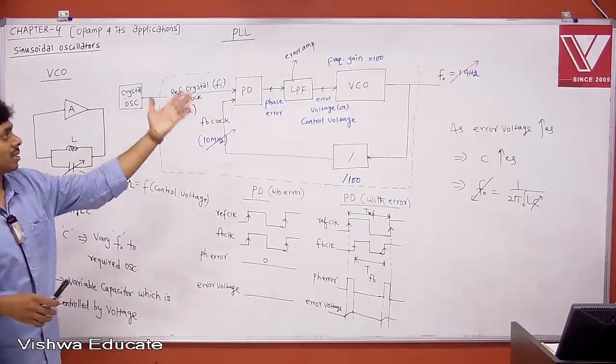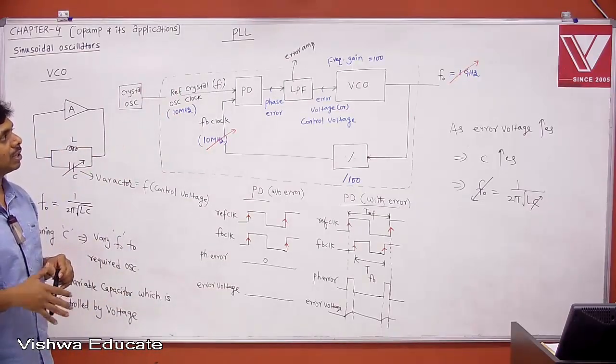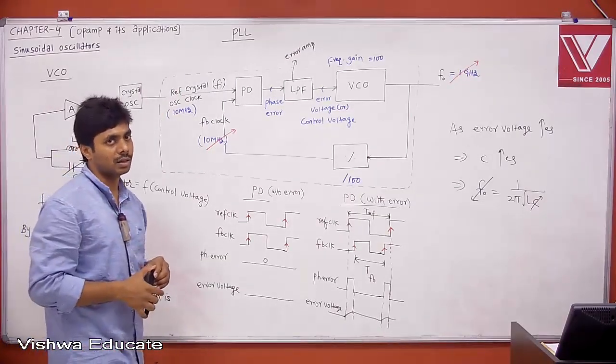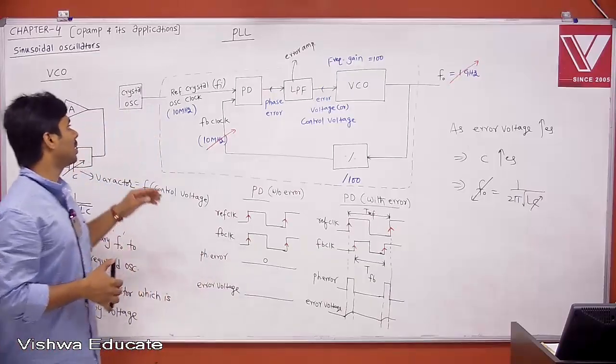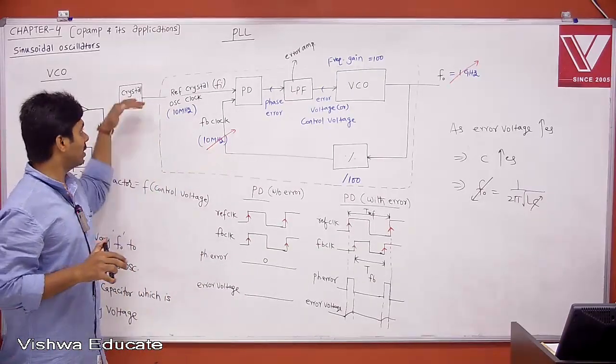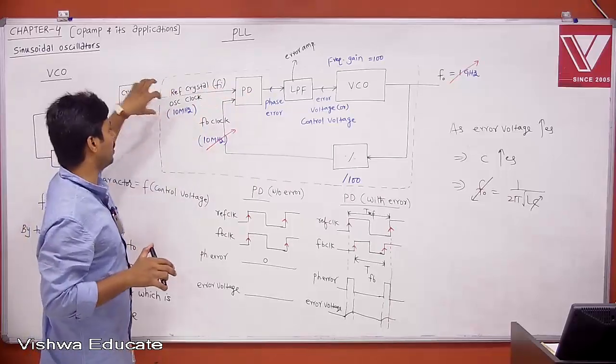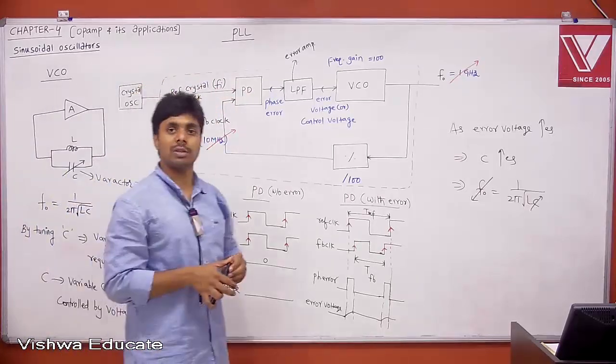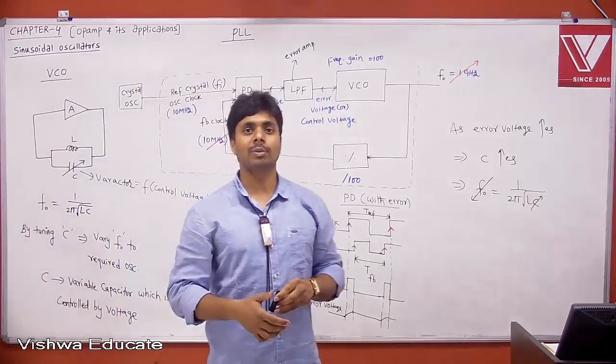But here we have amplification, frequency amplification. Similarly, whatever reference voltage you want, you can get it. For example, if you want directly 10 MHz and that is enough for me, then there is no need for a PLL. You can directly drive the crystal output with some buffer amplifier, and drive your 10 MHz to whatever circuits you need. That is what earlier people used to do.